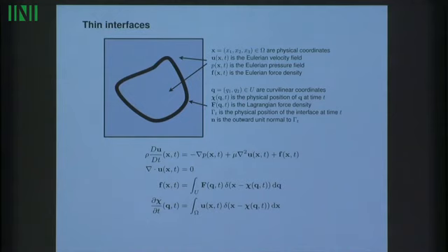So the immersed boundary formulation of this fluid structure interaction system is a formulation that was introduced by Charlie Peskin in the 70s in his PhD thesis work, which was in physiology on modeling heart valves. But what we have is the incompressible Navier-Stokes equations augmented by an Eulerian elastic body force. This is a body force density with respect to the three-dimensional coordinate system, x1, x2, x3.